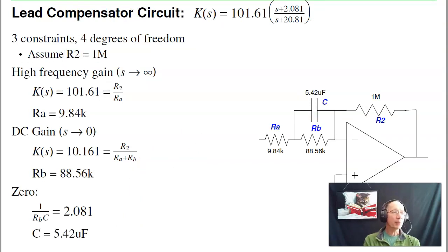If I want to implement a lead compensator, there's a couple ways to do it. In hardware, what I can do is build an op-amp circuit to implement it. This is like a variable resistor. At DC, the resistance is RA plus RB. At high frequencies, like during the transient, it's just RA. So at high frequencies, like when the light turns green, the capacitor shorts out and I have a high input. Then in steady state, I back off. So this is kind of like an automatic flooring. If I give it a step input, I floor it and then back off. That speeds up the system.